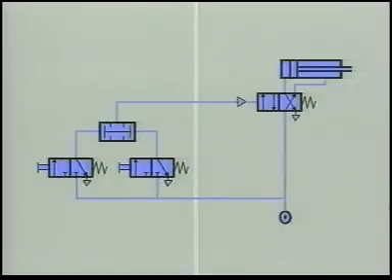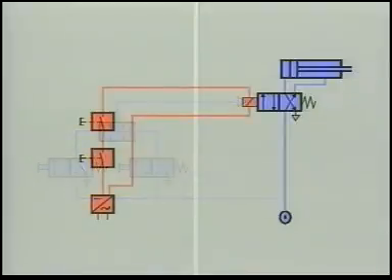Here the signals are generated and logically associated in the pneumatic control part, and the final control element is pneumatically actuated. In a corresponding electro-pneumatic control, there are electrical signal elements in the control part. In this case, signal processing is not carried out by a special device, but by connection of the various signal elements in such a way as to produce the function. The directional control valve, or more accurately, the solenoid valve, is now actuated electrically.